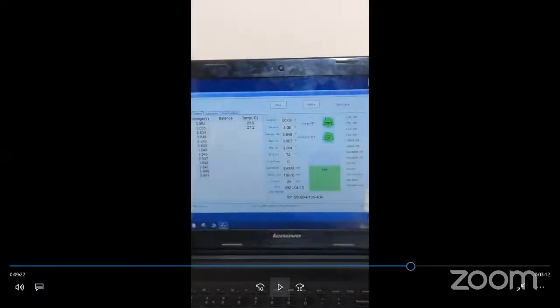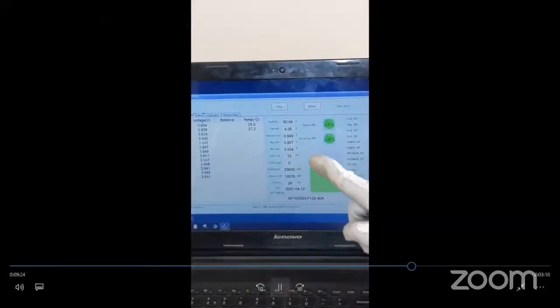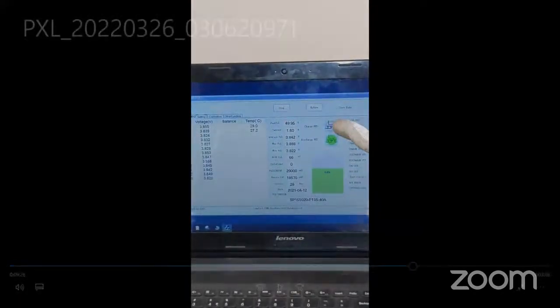As soon as the BMS detects 4 amps coming from the charger, the MOSFETs, which act like an MCB, will control it. This is the charge MOSFET which is in green state, which means on. Now it is supposed to go off, as it is above the parameters we have set. You could see it goes into gray color, which is the off state.